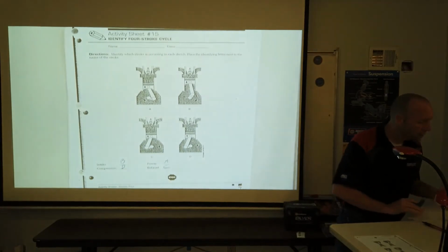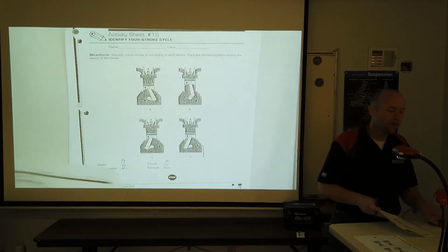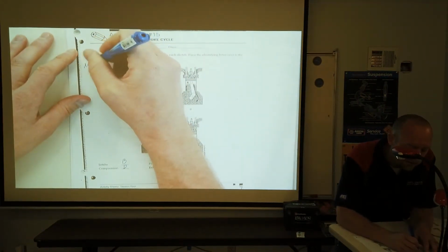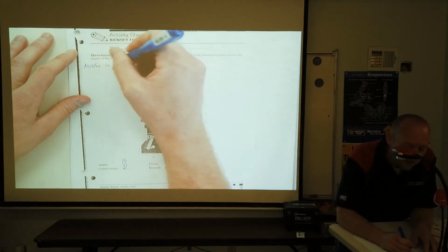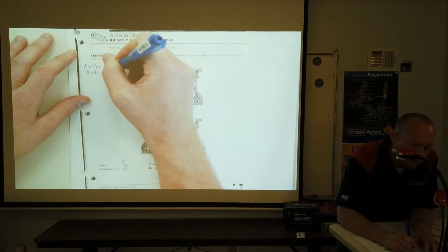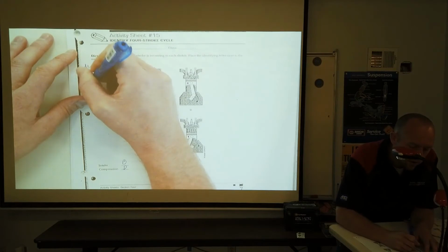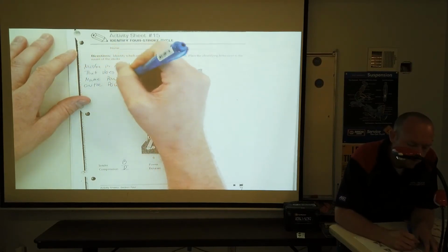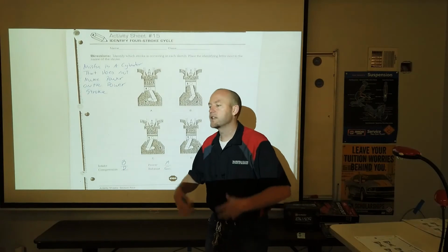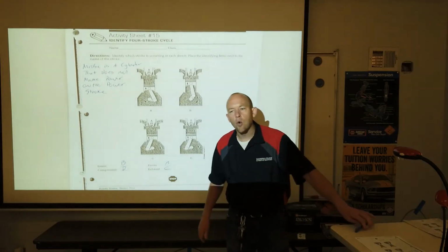Now, I want to give you a point of definition as we go through this: a definition of a misfire. I'll write this over on the side, and I suggest that you commit this to memory. A misfire is a cylinder that does not make power on the power stroke. So a cylinder that doesn't make power on the power stroke, or doesn't contribute to making power for that engine, we would refer to as a misfiring cylinder.